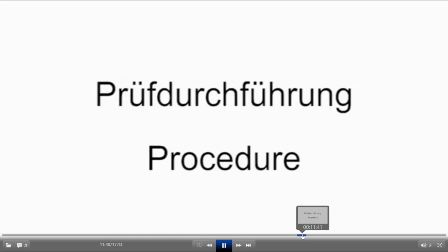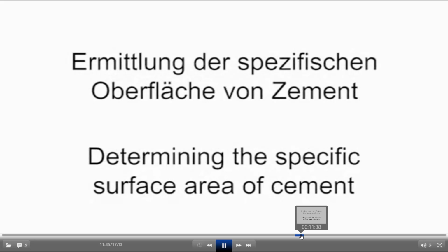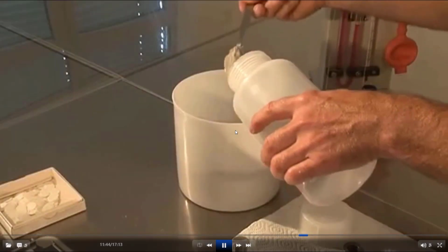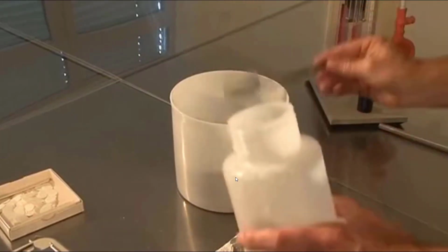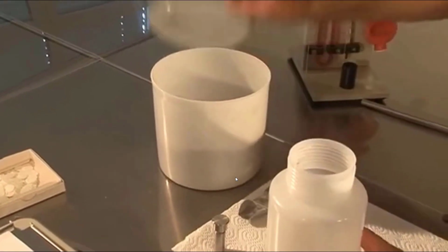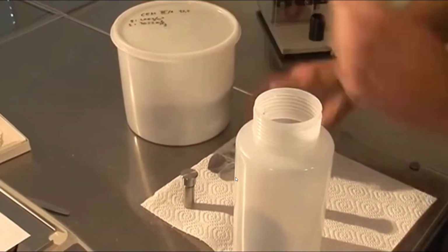Now it's time to calculate the surface area. Now you have a value of K for your reference material, and with the help of it you will find out the surface area of a cement. You have to repeat the process of finding the time lag between the 2 points of a manometer by repeating the same procedure that you have done for the reference material.